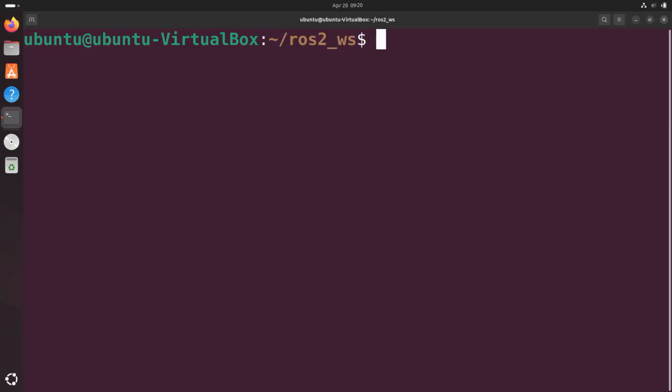And if you want to create your own custom 3D printed mobile robot in the future, all you have to do is use a CAD program, like Onshape, Fusion 360. You can use AutoCAD or SolidWorks. Just get a CAD program, and these tools will help you create the 3D models of your robot parts that you can then export into STL or Collada format for use in your URDF for the mesh file. But we've already got all we need thanks to Yaboom,